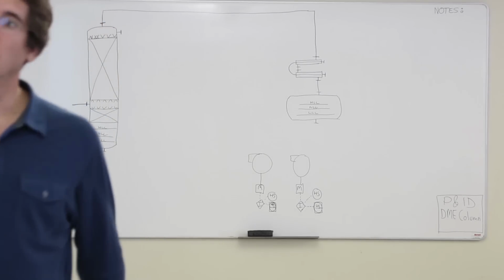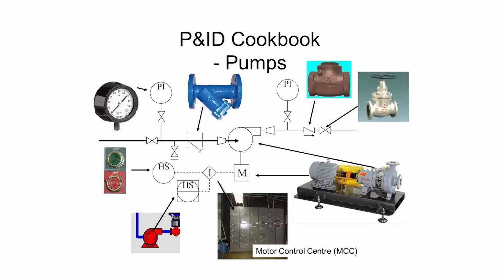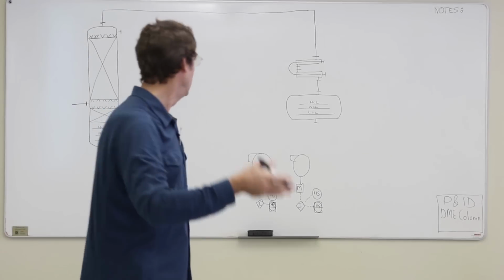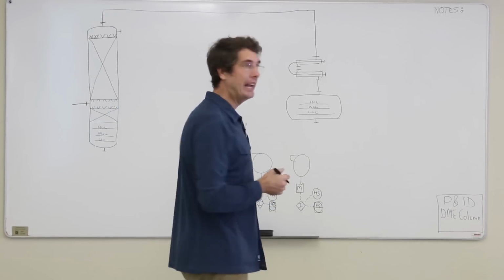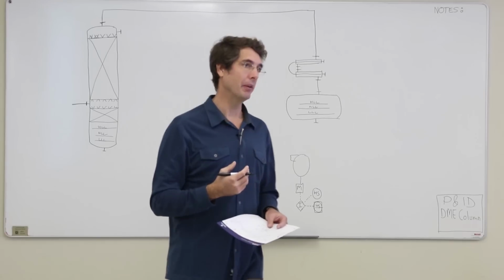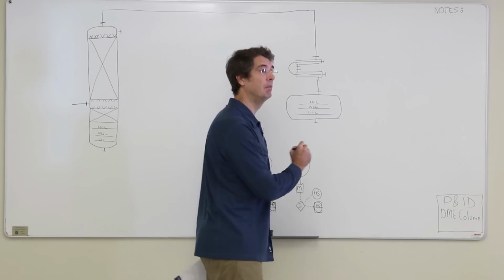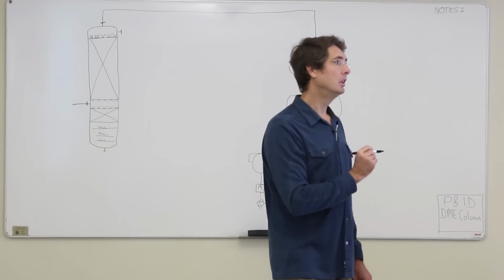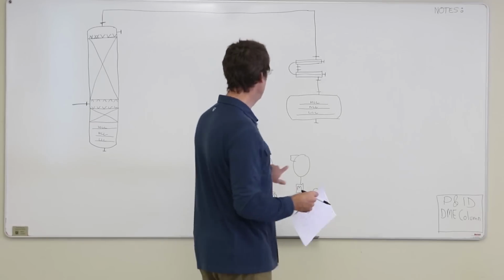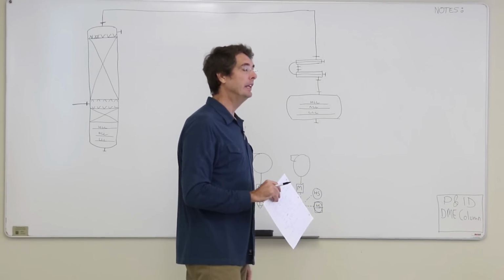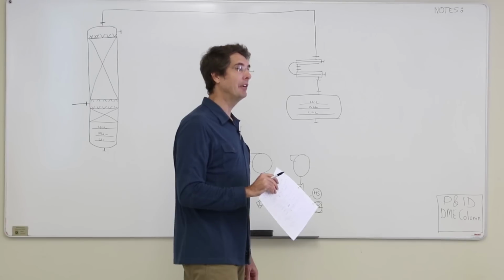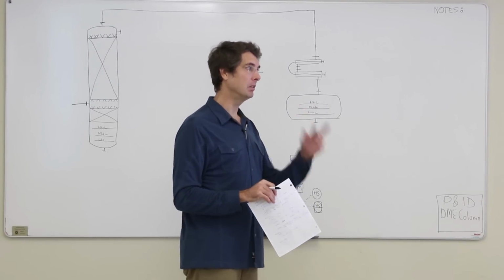What's the I? So the I right there is the motor control center. And the reason it's the same symbol as an interlock is because there are a lot of relays in a motor control center. Mike? So are those two pumps, like, just one of them is backup? Yeah, you've got two pumps, one's redundant to the other one. No, usually they'll just have one running in the process industries. Yeah, if you're in an HVAC system, they often have both running.